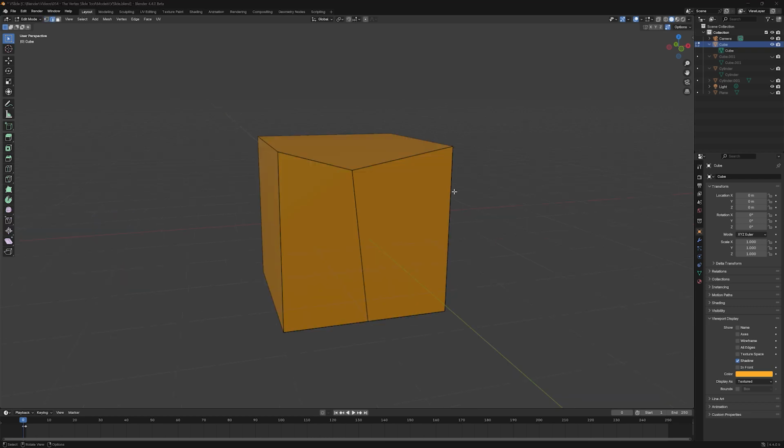To use this tool, we need to first activate Edit Mode's Vertex selection and select one or more vertices. After choosing the Vertex Slide tool in the toolbar, a yellow filled circle will appear over the selected vertex. This is the Vertex Slide's gizmo.